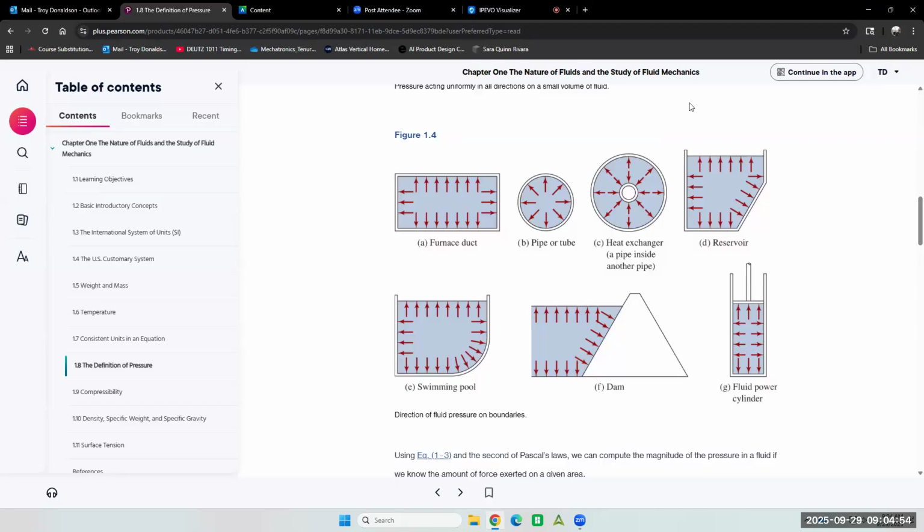Like if we have a furnace duct, the furnace is your heater in your home, pushing air. That air is under pressure. The only way we get that air into the room is we blow it with a fan. So that creates pressure in your duct system. That's the system that delivers the air to the register where the heat comes out. On some older homes, the primary return gets pretty big. So we blow hot air into the home, and then there's a cold air return that grabs the cold air and takes it back to the furnace. So essentially we are recycling the air in your home.